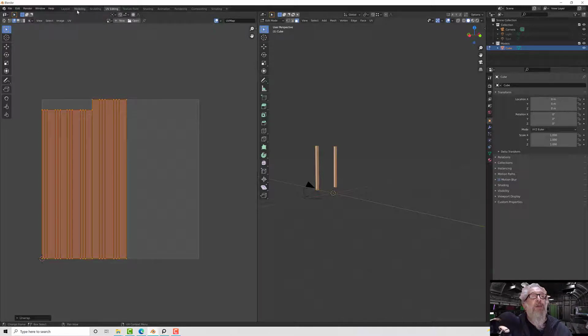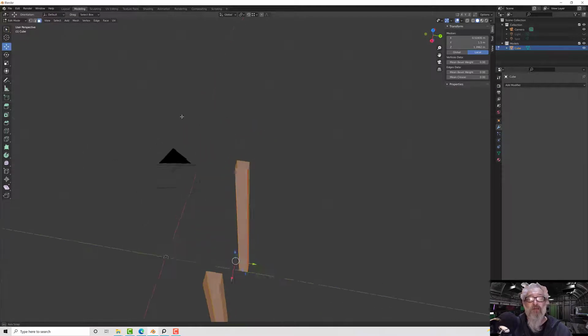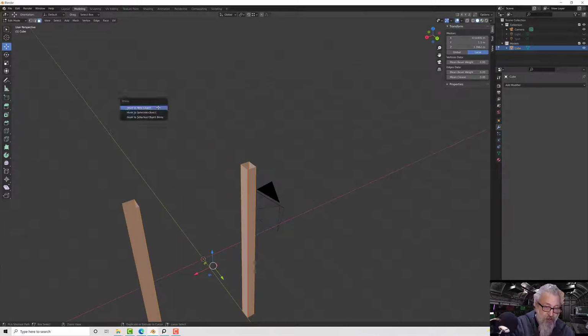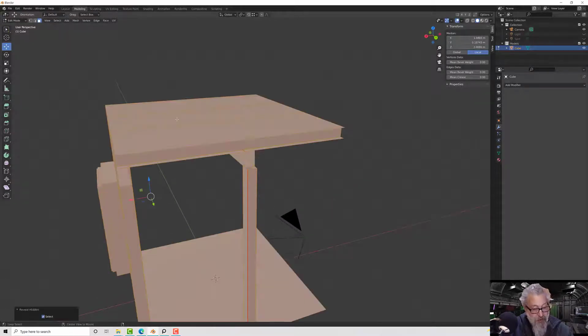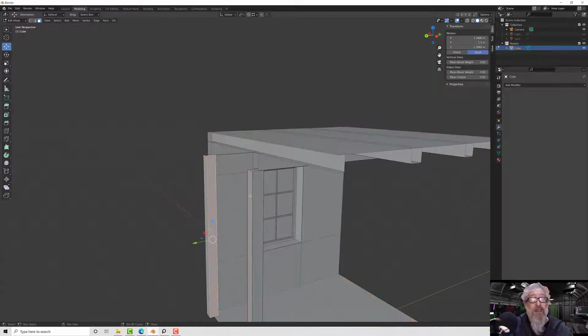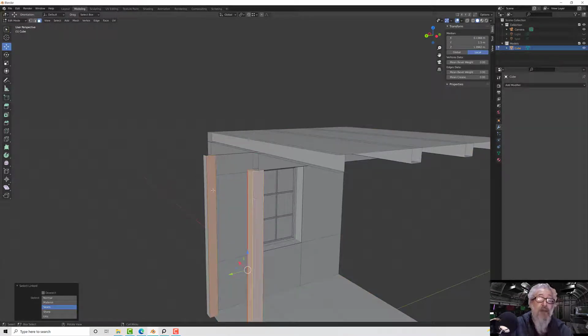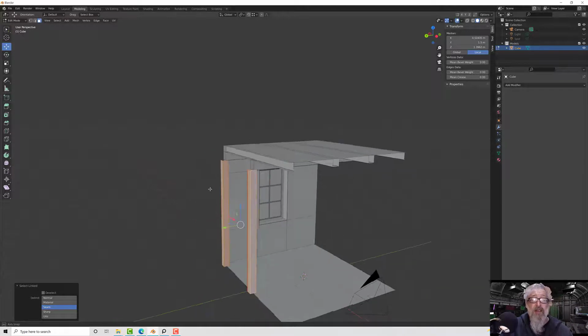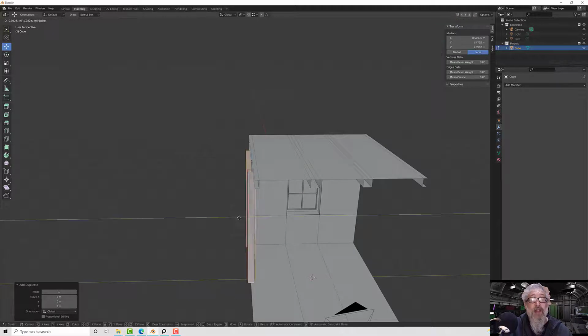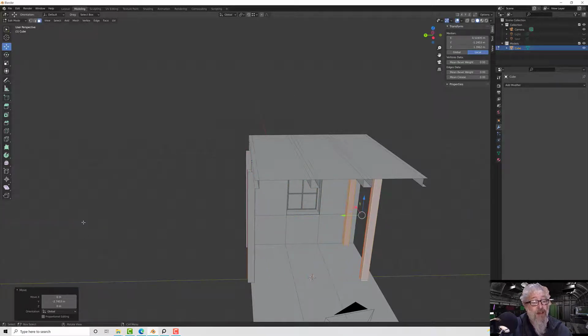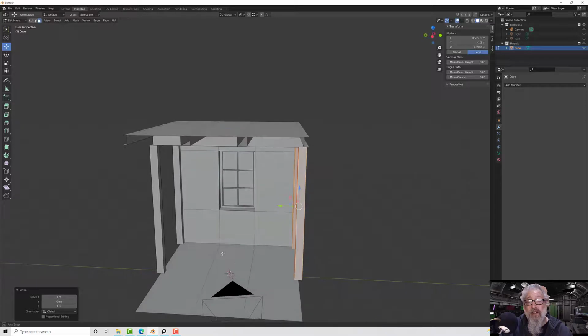And what did we want to do? We wanted to copy them to the other side. So let's go to modeling and press Alt H to J. Alt, whoops, that's Control, that's why it's not working. There we go. So let's select those and hit L, then point at the other one and hit L, and then Shift D, and then right click to put them where they need to be, and then move them to the other side. It should be -3 meters, and now we just need to cut them in half.